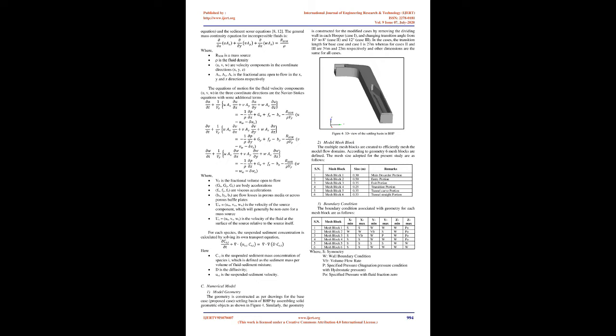The analysis in this study is fixated on the settling basin of BHP. The physical modeling of the settling basin has been carried out, and these data are used in our computation and analysis. 1. Physical feature. The intake is designed to withdraw a design discharge of 26 m3/s at the normal operating level of 720 m, 22.1 m3/s for power generation and 3.90 m3/s for flushing. The discharge from the intake is conveyed to 2 settling basins through 2 D-shaped feeder tunnels of 2.5 m x 3.0 m size. The feeder tunnels operate under pressure flow conditions.